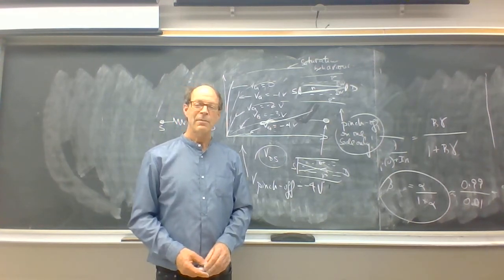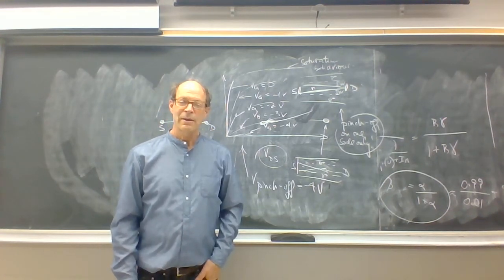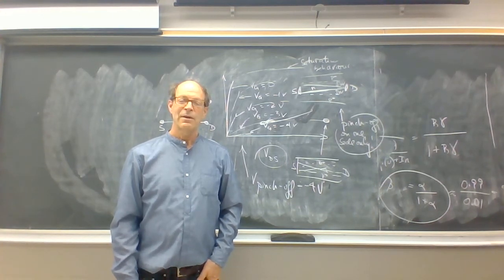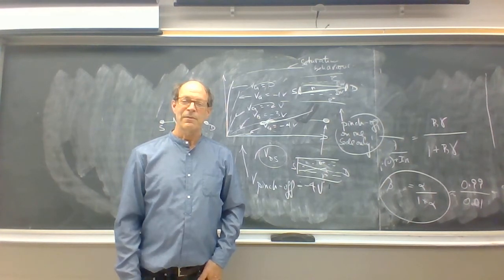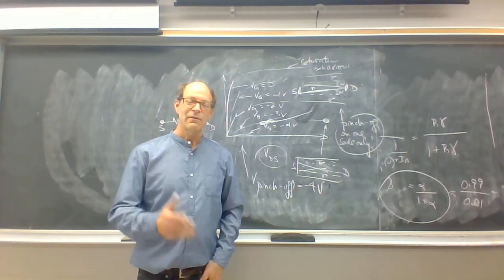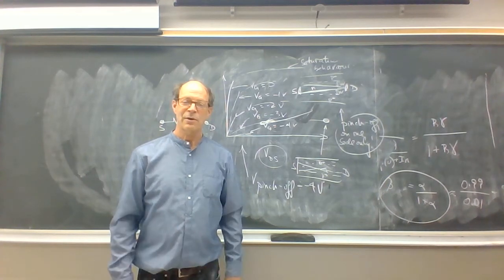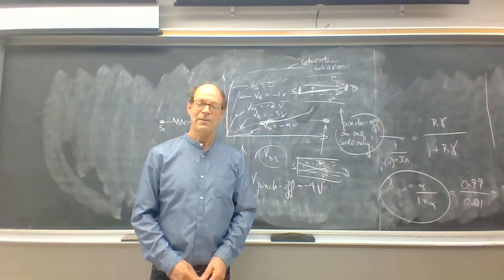On the other hand, a bipolar junction transistor is very robust and rugged, and it has important applications where you're trying to get high current output and behavior that's really dependable in a wide range of adverse conditions, such as noise and voltage transients, etc. It's a more robust device than a junction field effect transistor.